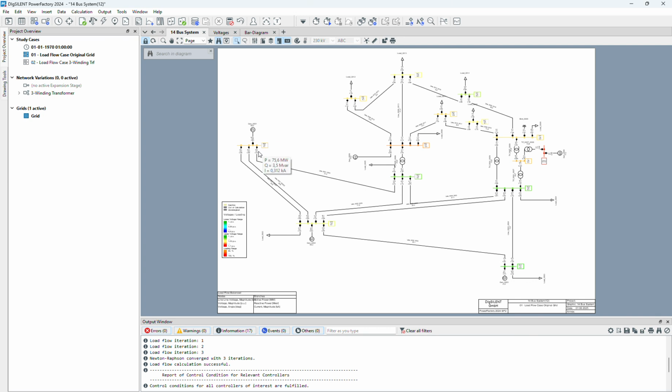And here you can see the current that is going through this line is 312 amp. So we assume that this is the rating current, but the rating current should be 3 times of this one, but we assume that this is the rating current. And we should add 25% to this one. So 312 amp multiplied by 1.25 will be 390 or around 400 amp.